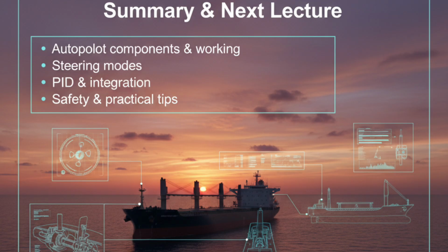Most importantly, we discussed safety and redundancy, manual override systems, alarms, dual sensors, and the critical requirement that autopilot must never replace human supervision. Automation supports navigation, but responsibility always remains with the officer on watch. This knowledge is extremely important for marine engineers, deck officers, and ETOs, both for onboard operations and for competency examinations. Understanding how autopilot interacts with hydraulic steering gear is essential for safe and efficient vessel control.